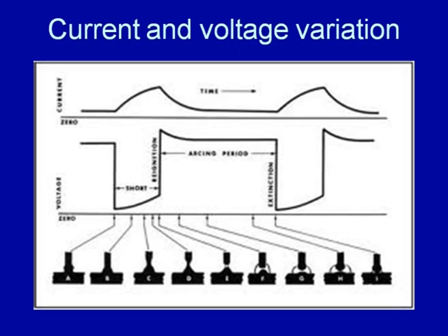In this stage thinning is taking place and the molten metal drop is about to detach, and as soon as the detachment takes place, the arc voltage suddenly increases from this level to this level.